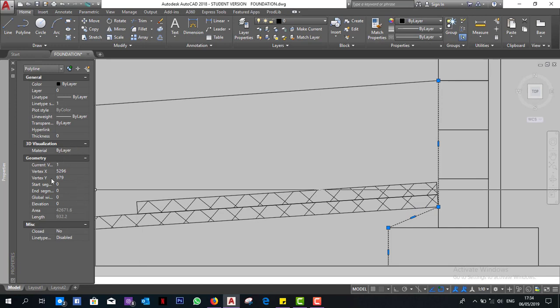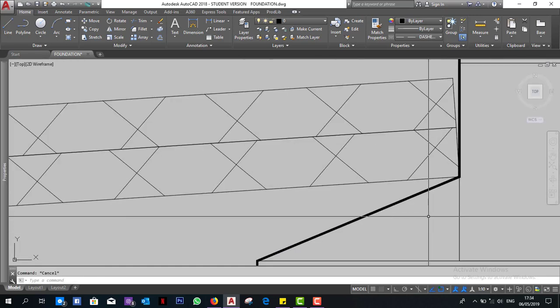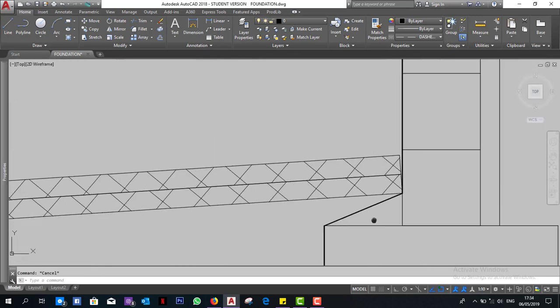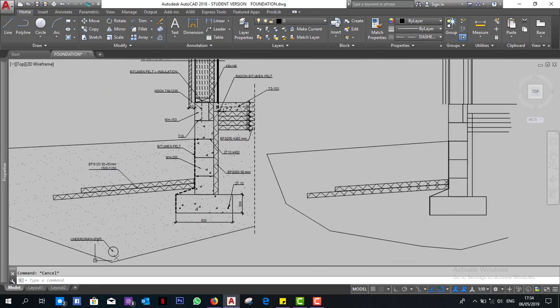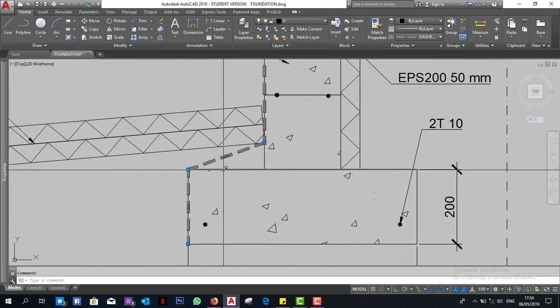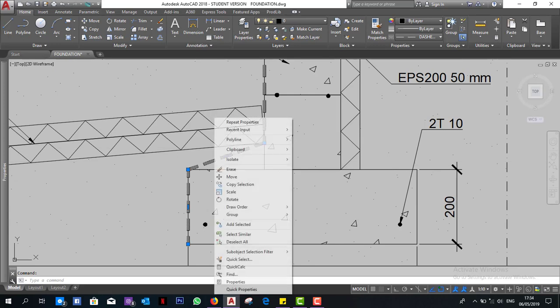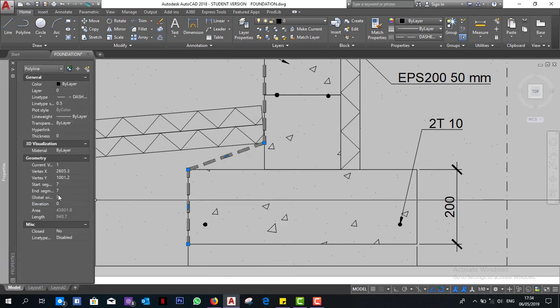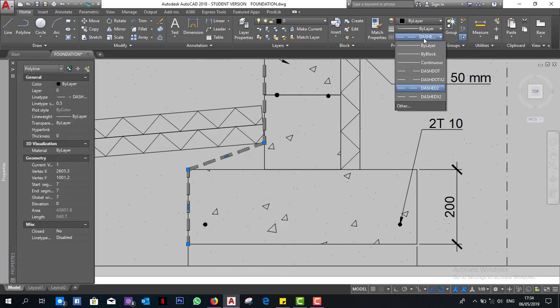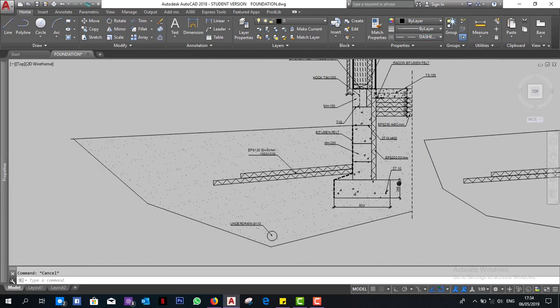So as we see, we have all these options, but what we're interested in is the global width. This is a good option for the polyline because you can make it thicker. And let's say that we're going to do global width 2. What happens? We are having a new thickness to our line. But let's see the configuration of this thing. We go to properties and we have that the global width is 7, the type is -2, not -x2, sorry guys.